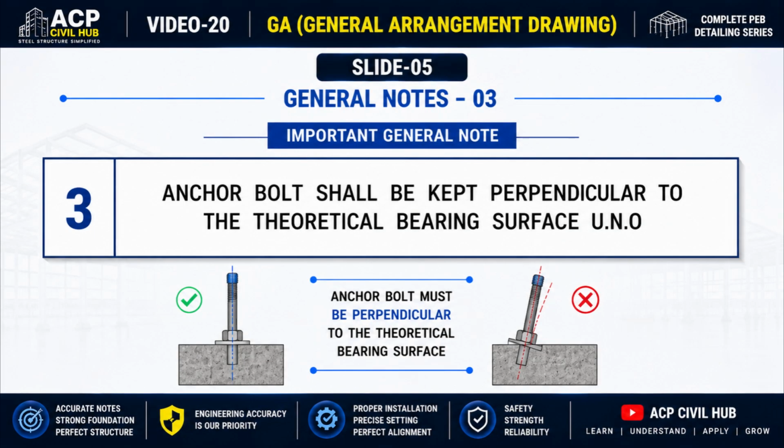Now let's understand General Note number 3. This note states that the anchor bolt must always be kept perpendicular to the theoretical bearing surface, unless noted otherwise in the drawing. In simple words, the anchor bolt should stand perfectly vertical, forming a 90-degree angle with the bearing surface of the foundation or pedestal.